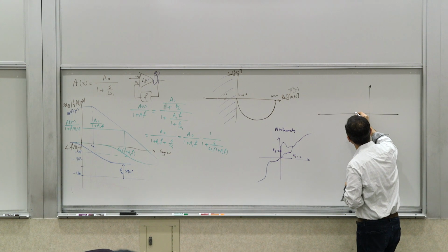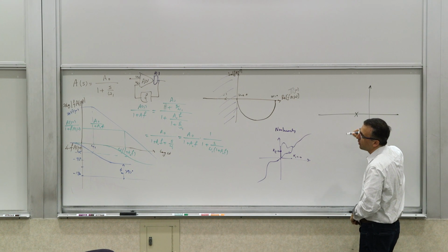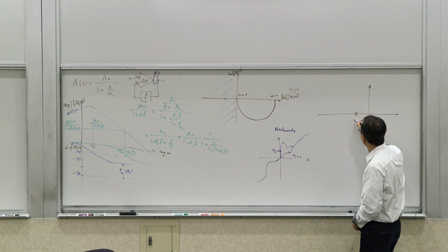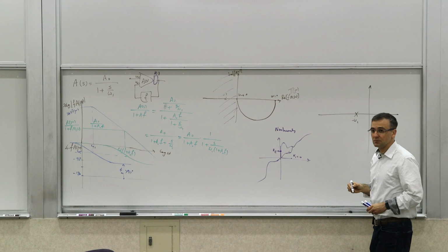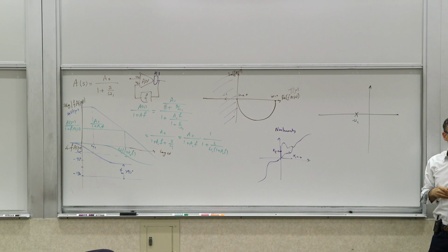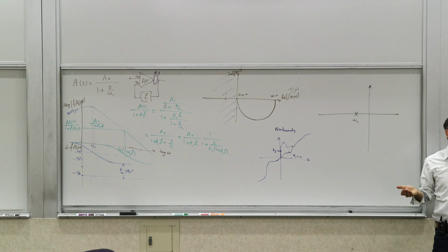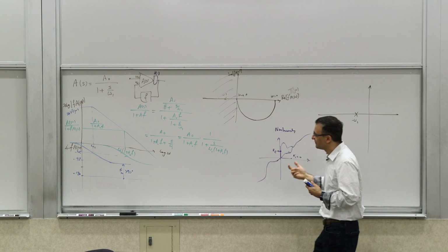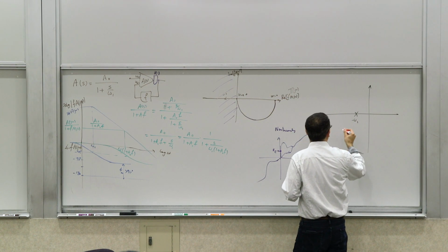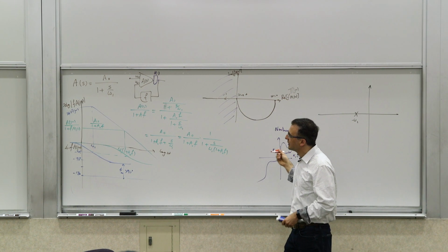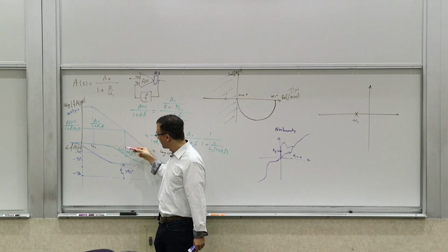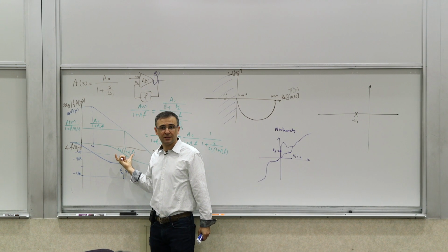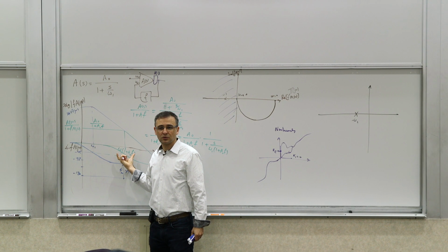So we are starting with a single pole, right? The single pole is at whatever frequency, like omega 1. This is where the pole is originally for the open loop system, or when f is 0. When f is 0, that's where the pole is. Now, as you increase f, as you increase the amount of f, what happens to the pole? The pole's absolute value increases, right? It's going to a higher frequency.